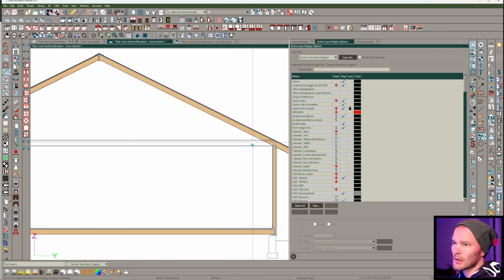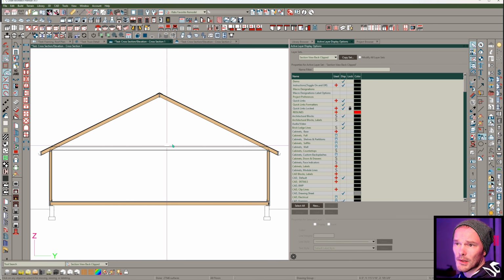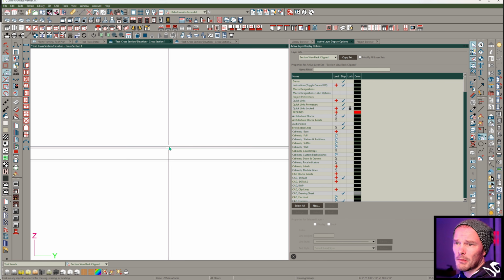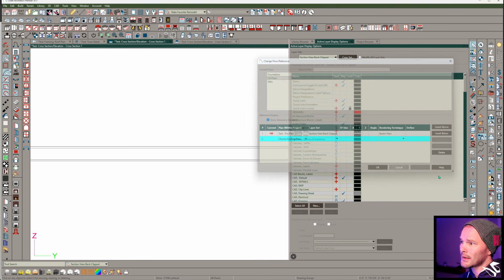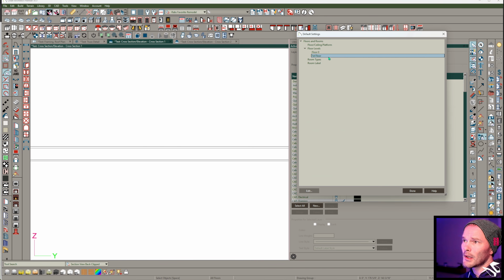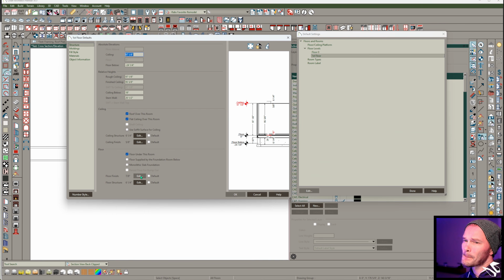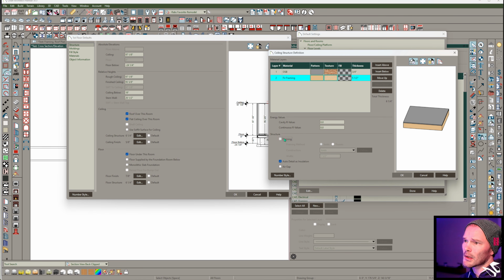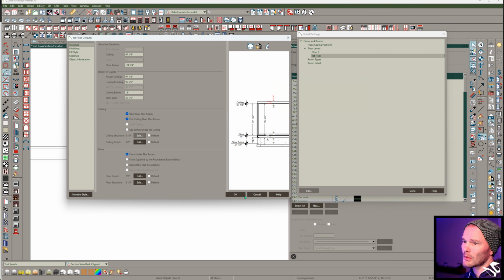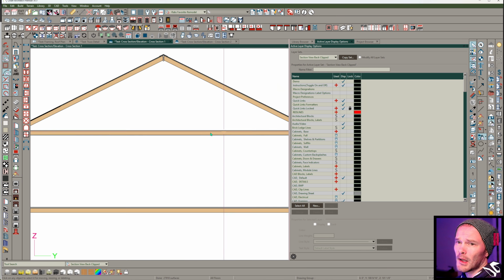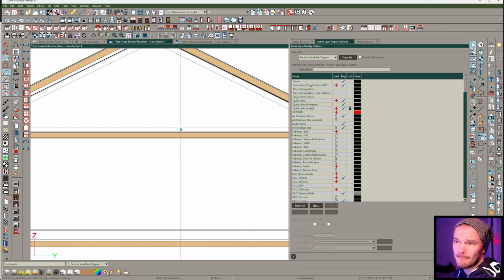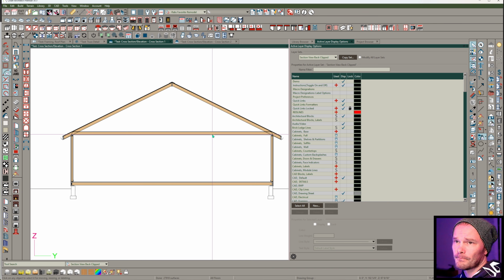Interesting. Not seeming to give me my ceiling trusses, but I know they're there. But, oh, maybe I unchecked that as framing. Someone must have caught that, right? Someone must have caught me screwing up and didn't tell me, because this isn't live and it should be. Ceiling structure. This is what I unchecked as framing. Oops. Mistake coming. Framing. Yeah, so that kind of depicts a floor. Is that what we want? Maybe that's all we needed. Cool.